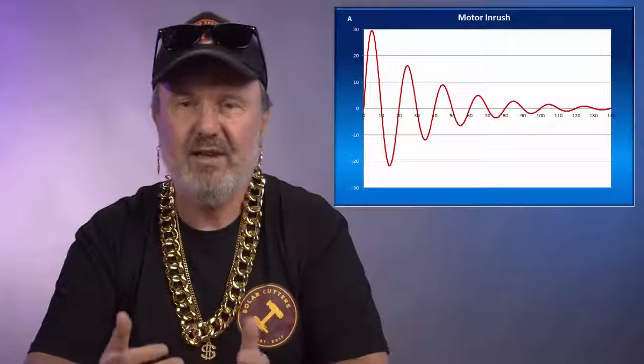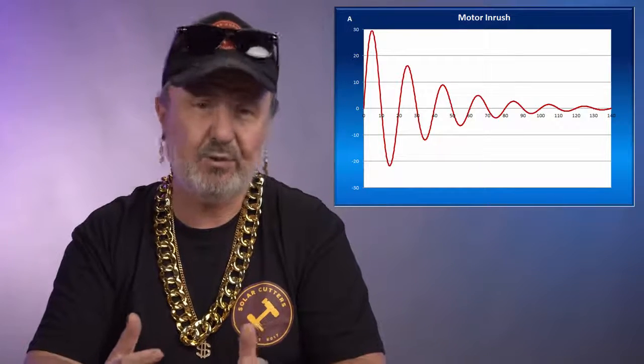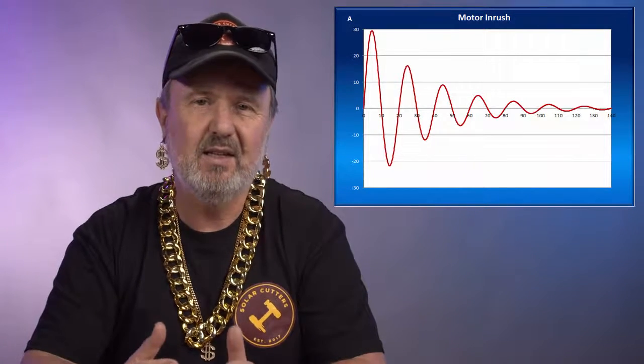But for many, a pressure pump is the problem load. It will often draw 3, 4, 5, up to 7 times its run power as it starts. So from a maximum demand calculation perspective, we need to consider not just the coincidental maximum demand of loads, considering power factor, but also considering surge demand.